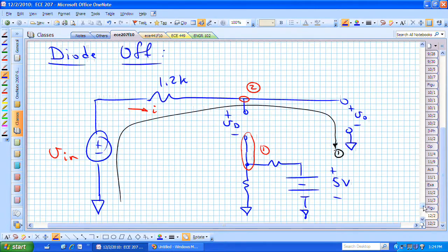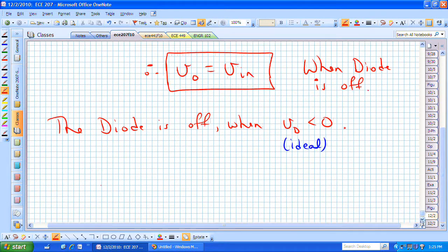And what is V sub D? Well, if we look at that, we can now say that if we called this voltage 2, and maybe this is now voltage 1, we can say that if we did a KVL around there, we would have minus V sub 2 plus V sub D plus V sub 1 is equal to 0, or V sub D is equal to V sub 2 minus V1.